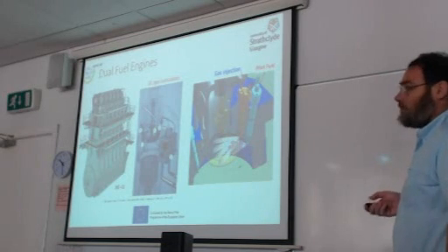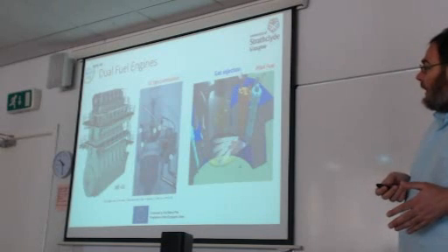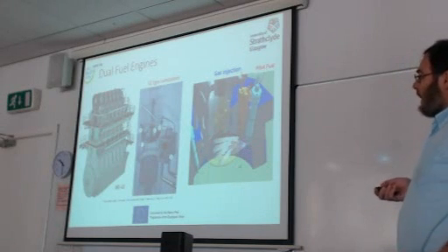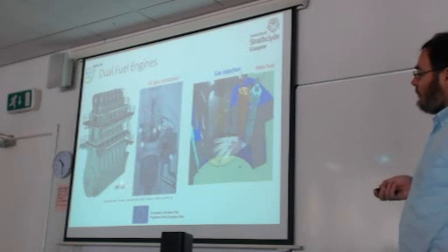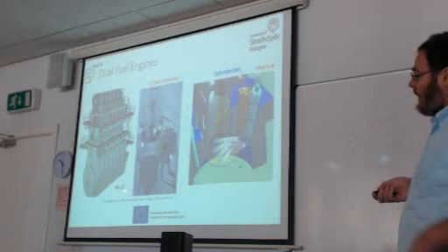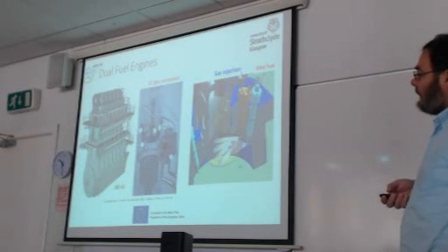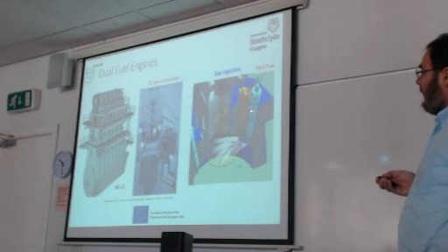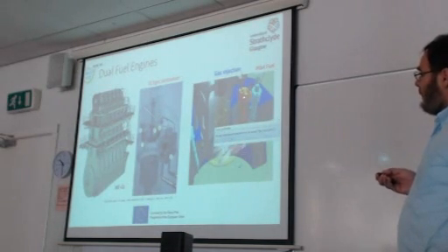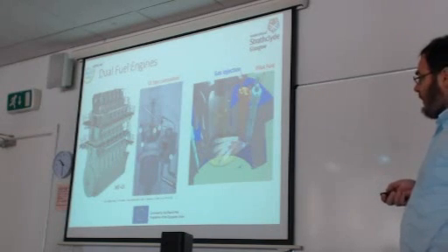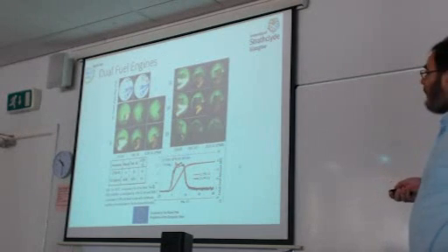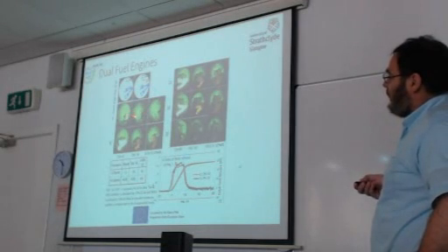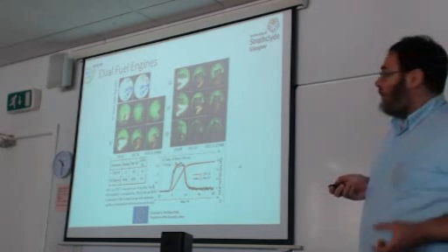So the concept here is that natural gas can be injected by a separate injector. So you can see here the gas injection, the pilot injection. The two fuels are injected simultaneously, and we have a diffusive combustion of pilot fuel and gas fuel at the same time. So the engine is called the GI. So it's the typical engine code plus GI, gas ignited or gas injection, if I remember correctly. In this case, a pilot fuel injector and a natural gas injector, of course, are required.